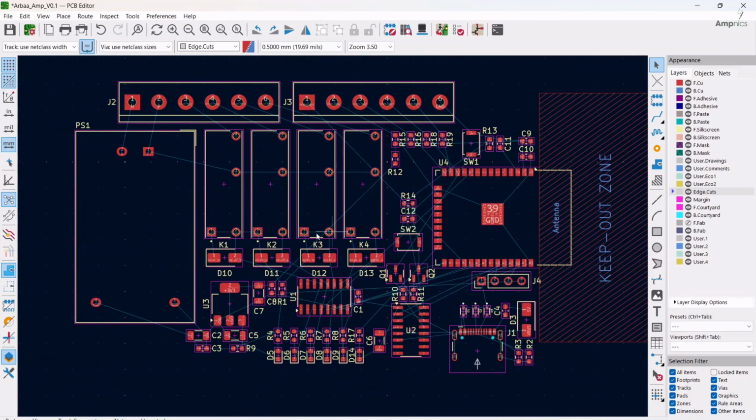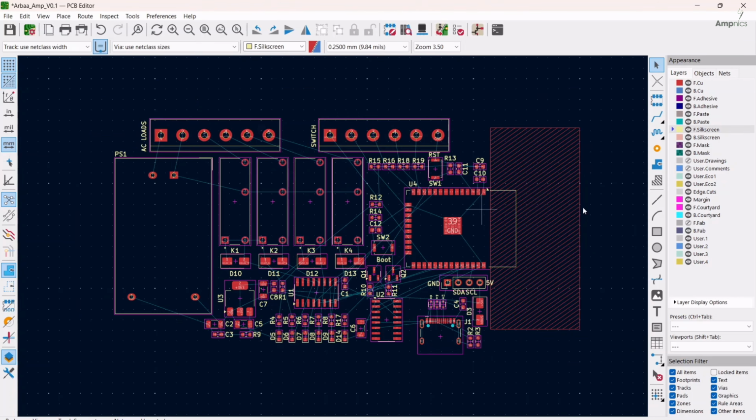Placing the components in your circuit takes time, and how much is totally up to you. The more time you spend on it, the more beautiful or more efficient a PCB you get. Okay, now we will make the board outline. First select the edge cut layer. Okay, select the edge cut layer, then we will